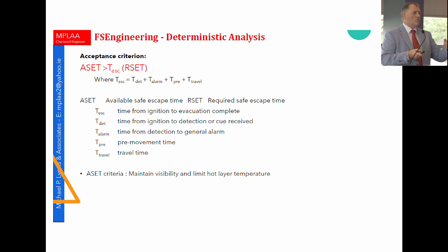Where we are in this room, there's a door out to the open air immediately within a short travel distance. So our travel time is very, very short. All of that has got to be designed into your required safe escape time, and in all of the scenarios, it's got to be less than the available safe escape time based on the configuration of your building.